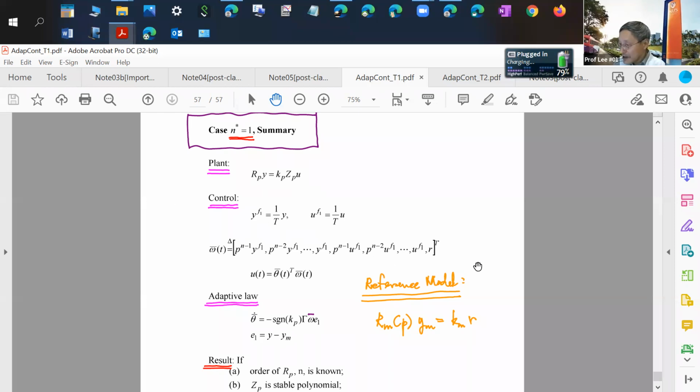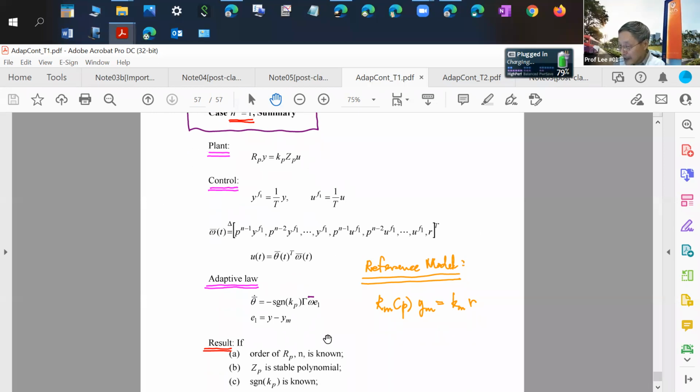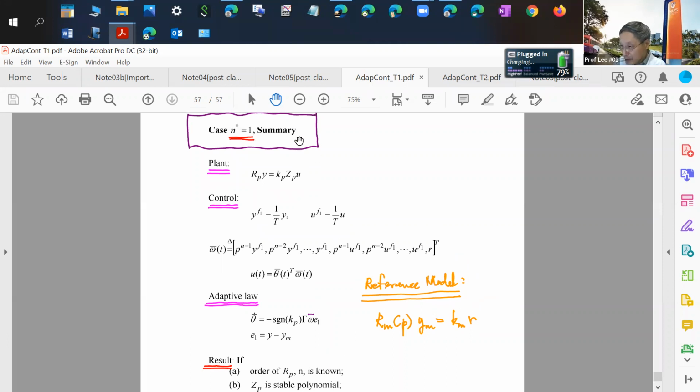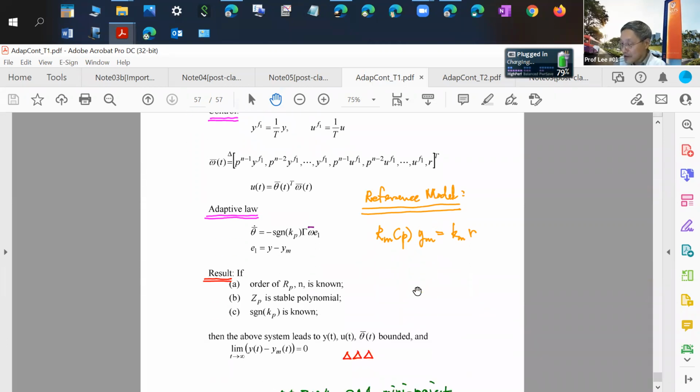So this part of it did not depend on relative degree equals 1. This part of it is what you would do for a general n-order system anyway. But the moment you use this adaptive law, relative degree 1 comes in. And remember what we said was that it was guaranteed that all signals in the system are bounded and the tracking error was guaranteed to go to 0, which you will be able to explore and really see in your CA1. So that to me is quite exciting, without all the very messy signal processing coming in. Let me not jump ahead of myself.